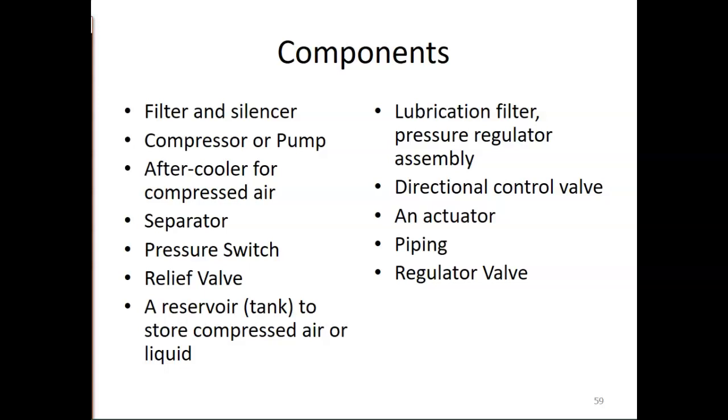Compressed air can get really, really hot because you're basically forcing a bunch of molecules together, so they start bouncing off each other. So one of the things we can add to a pneumatic situation is what's called an aftercooler. And this just takes any hot air that's coming out of your compressor and brings it down to a cooler level so that you don't end up heating up components, because heat is actually quite the enemy for us, isn't it? Why is heat the enemy?